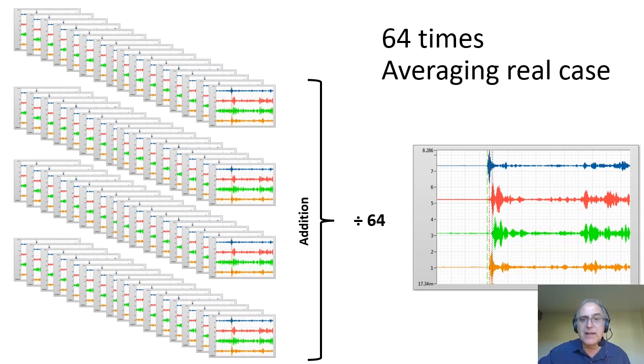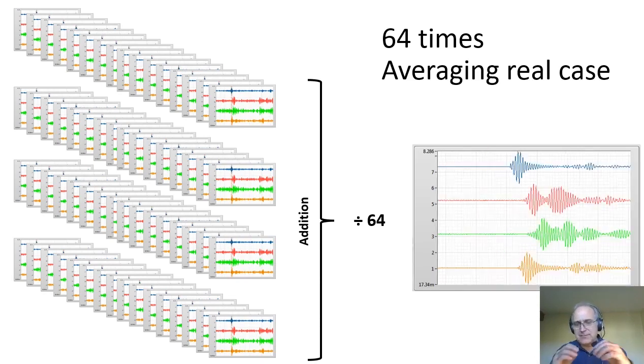And then what we can do is zoom in. This is the same thing, but I have zoomed into the waveform, and I can clearly identify the time of arrival. So that point, this point here, it's very, very clear. It's totally flat, and then I get the acoustic pressure waves.